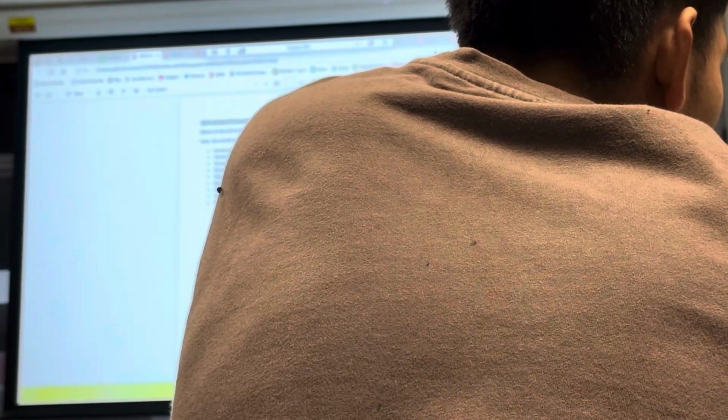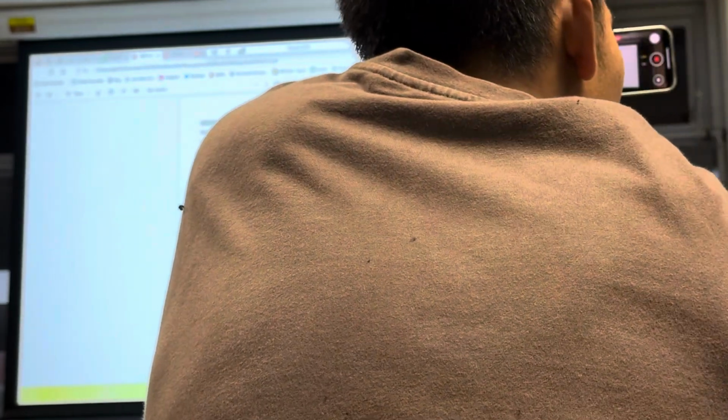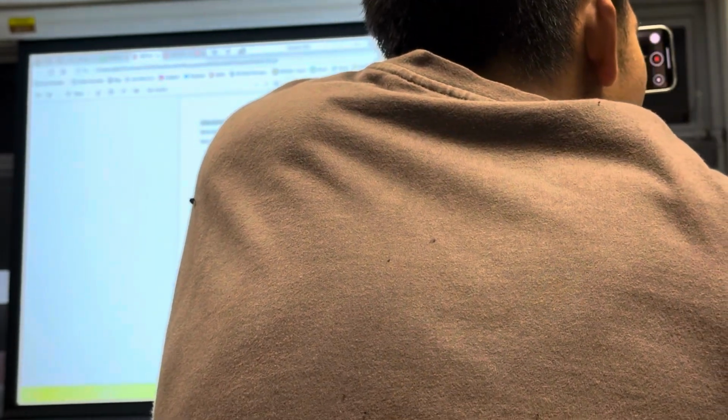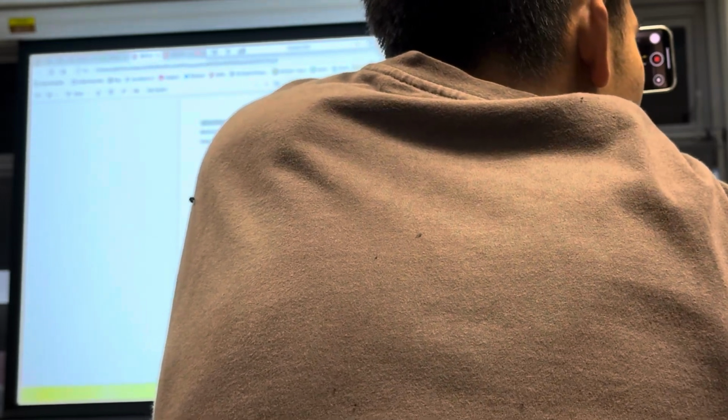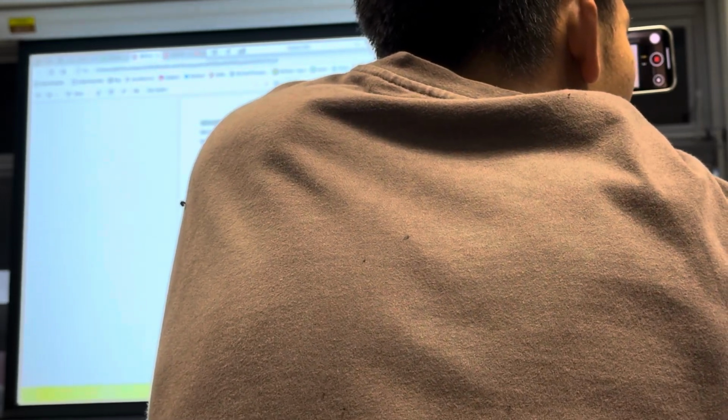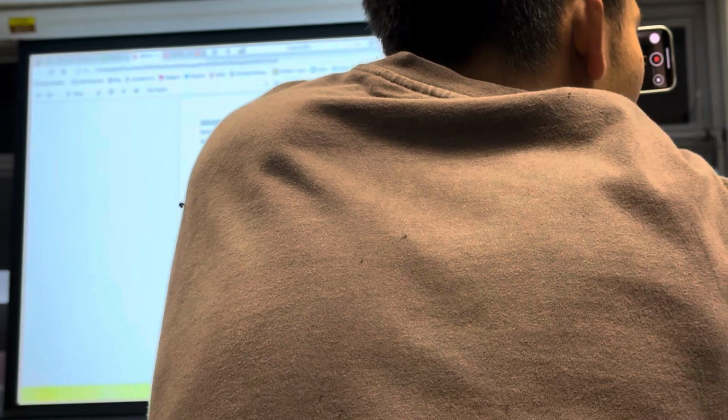So, although assignment 1 is really easy and shouldn't take too long, it would definitely pay just to have a look at where those points are, so you don't put your alignment right through the middle of everything. Alright, well look, this is real world learning here. It's happened to me many times. I think probably one of the worst things to do is to not check if there's any iwi archaeological stuff on site and you plough right through the middle of it with your alignment, because that immediately, problem.